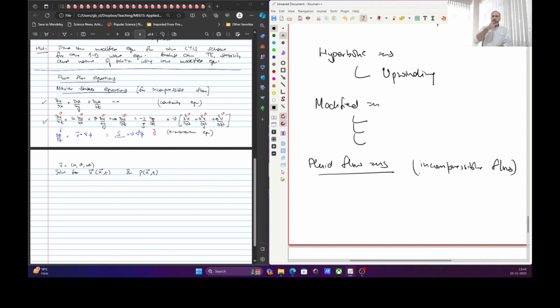Because engineering wise speaking, mostly, especially in mechanical engineering, you deal with situations where the flow can be considered incompressible. Mach number less than 0.3, even air can be considered incompressible. And actually computation, CFD wise, solving incompressible equations is more complicated than solving compressible flow equations. So it's even more important to talk about the difficult ones, because compressible ones are much easier.